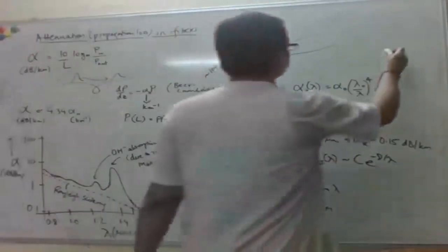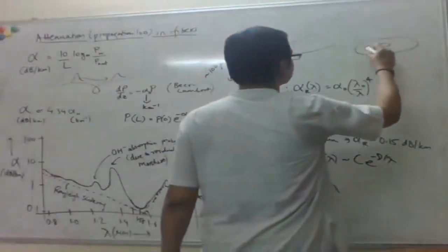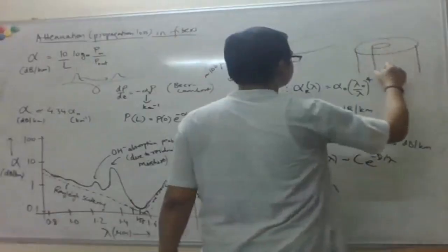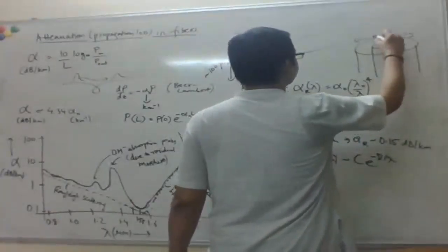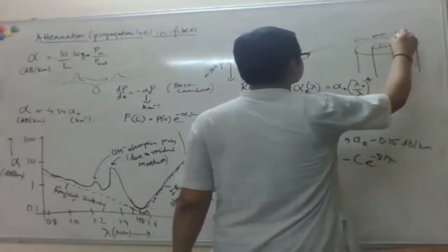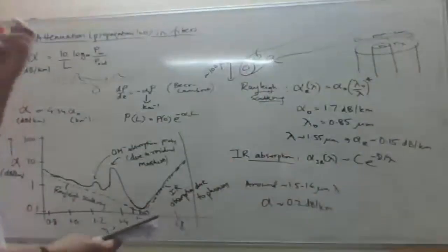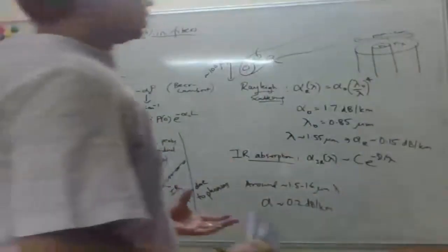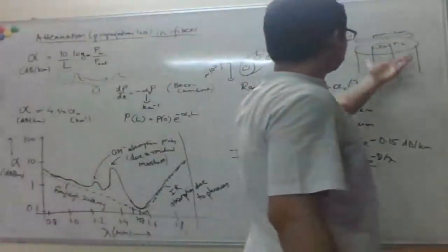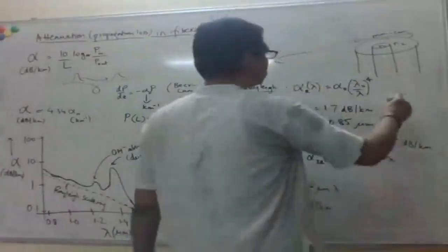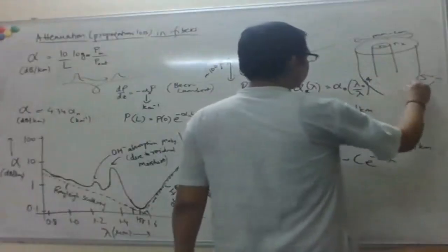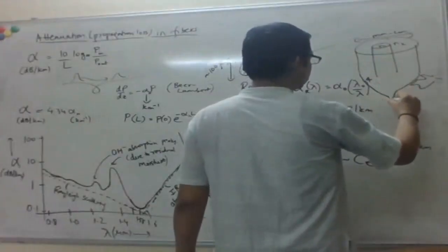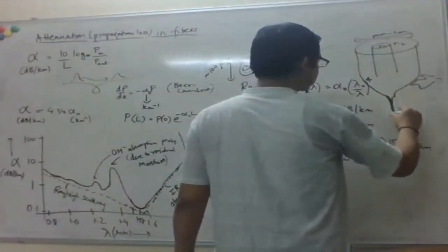So what you do is you start with a preform which is much bigger, right? So you start with some cylindrical rods, of let's say millimeter to centimeter size, so much bigger, right? The techniques for shaping glass are well developed. So you make these big preforms, and then what you do is basically heat them, right? And then you have a thing which basically pulls this.